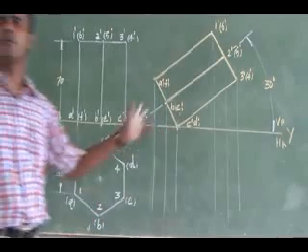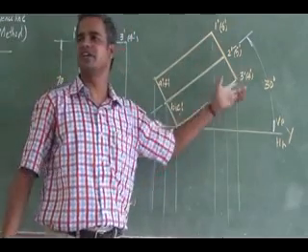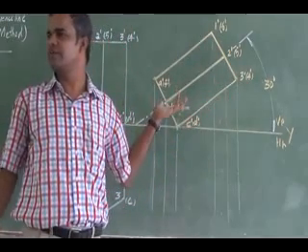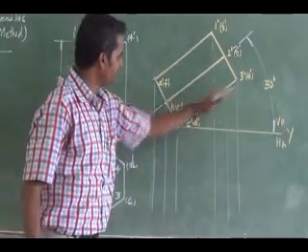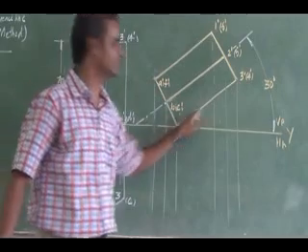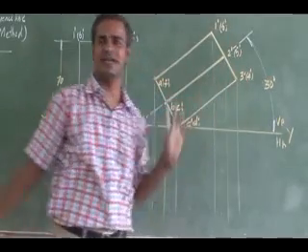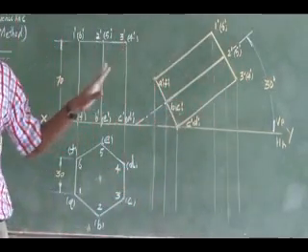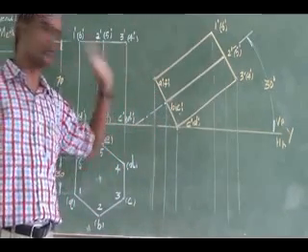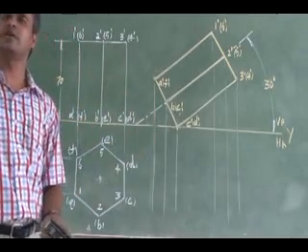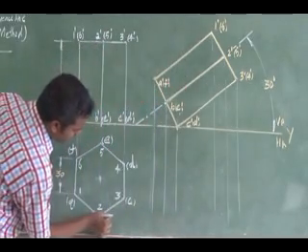You can ask, why sir, you have measured 60 degree for the base, when the axis is 30 degree, the side itself is going to be 30 degree. For a prism it is okay. If it is a pyramid, you will be struggling. For a prism, I can measure 30 degree, mark CD, and measure 70 mm. I can mark 3, 4 and proceed, I can reproduce it. But for a pyramid, it will be difficult, so you have to convert that. You follow this 60, convert that to base inclination, then you proceed. Then extend this previous.